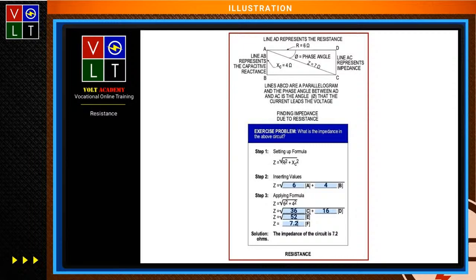Now, if I look at a resistance circuit here, we're doing sort of the same thing. When I look at just basic resistance, it has an effect on the circuit when connected with capacitance and inductance, like we talked about. When I'm talking about a purely capacitive or inductive circuit, the current either leads or lags the voltage by what? 90 degrees, which is what we just talked about. So that's how we're sort of tying all this in. Now, if the resistance is connected in series with these circuits, the resistance always decreases what?